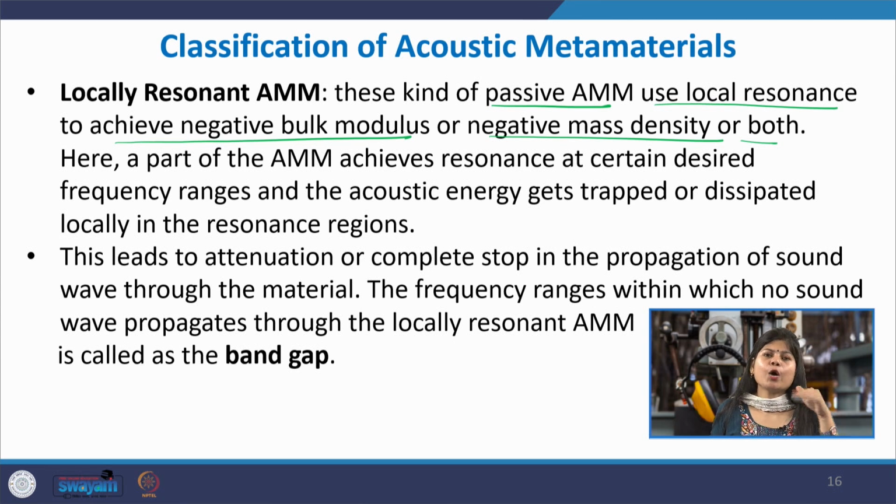And just like how we had studied in the case of Helmholtz resonator or the other resonance type of absorbers, whenever the resonance is there, basically the sound wave that is hitting at resonance, the sound power or the sound energy is getting used up in vibrating the resonating element at high amplitudes, and this leads to the use up of the sound power and its lowering down.